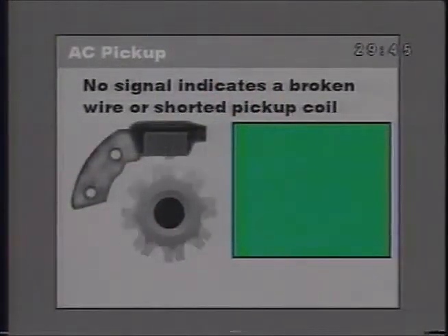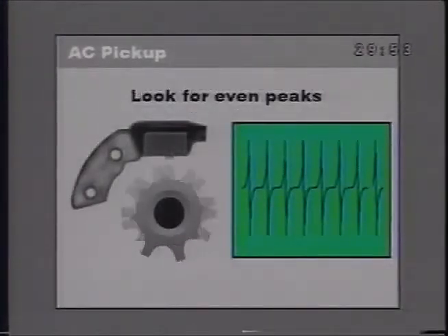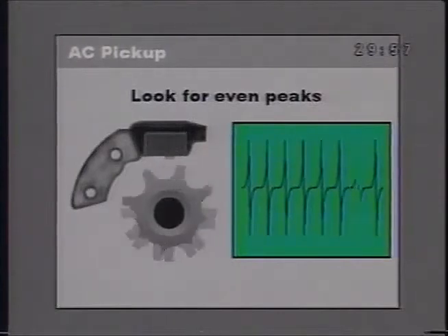One of the first things you're looking for is a signal. No signal indicates a broken wire or shorted pickup coil. As long as you have a signal, check the signal amplitude or voltage level. Look for even peaks.